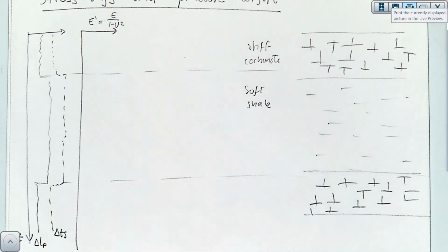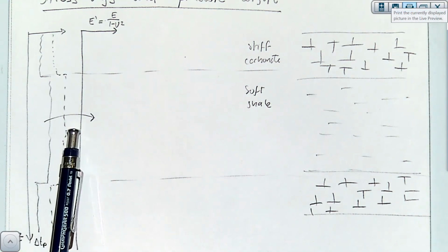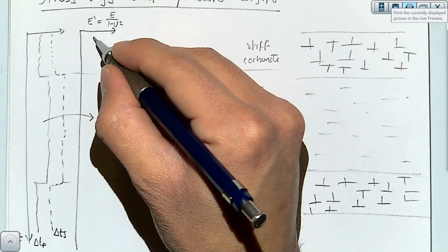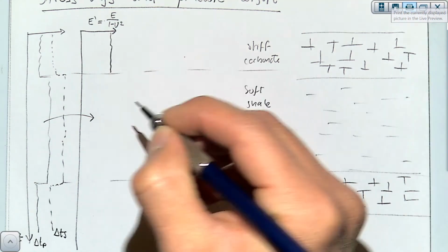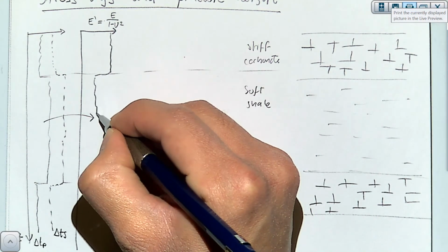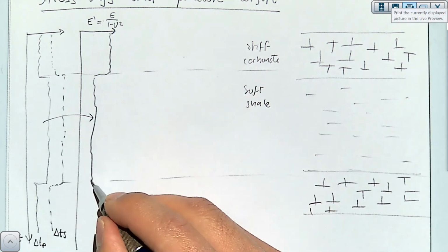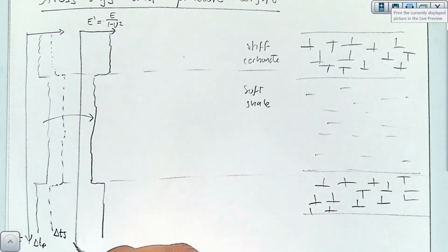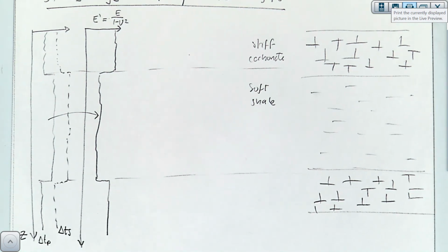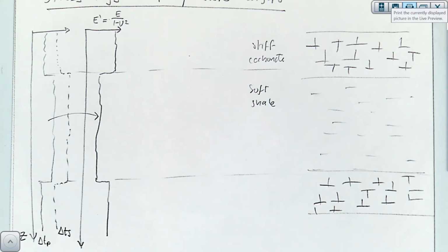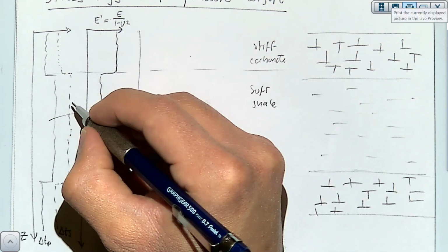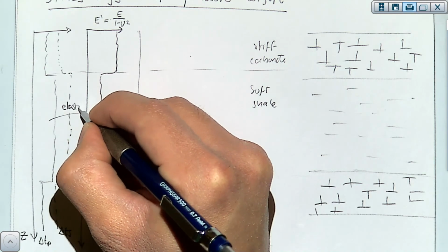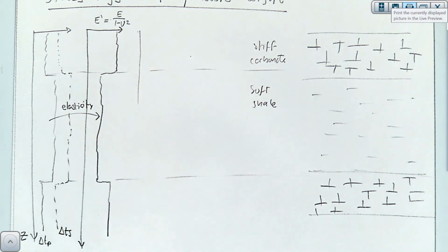And with these two, and with equations that we're going to see in a bit, you can calculate what is the stiffness of the rock. And probably in this case, as we were saying, this is going to be stiffer, and when it gets to the shale, we're assuming it's going to be softer. All of this is with depth. Okay. Basically, to go from here to there, we just apply the equations of elasticity.